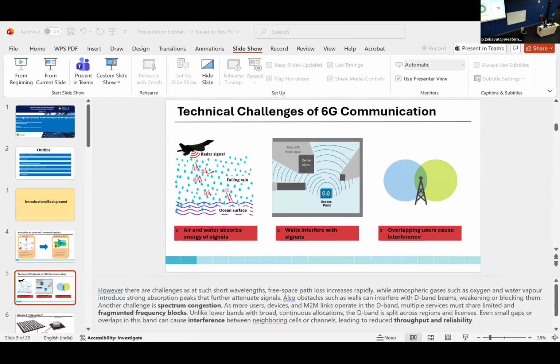So these diodes create four switching states where all the diodes can be switched off, or they can all be switched on, or only the top ones are switched on, or only the bottom one is switched on. And this shifts the resonant frequency through creating effective inductance and hence tuning the stop band across the D band spectrum, enabling reconfigurable electromagnetic interference suppression for 6G.